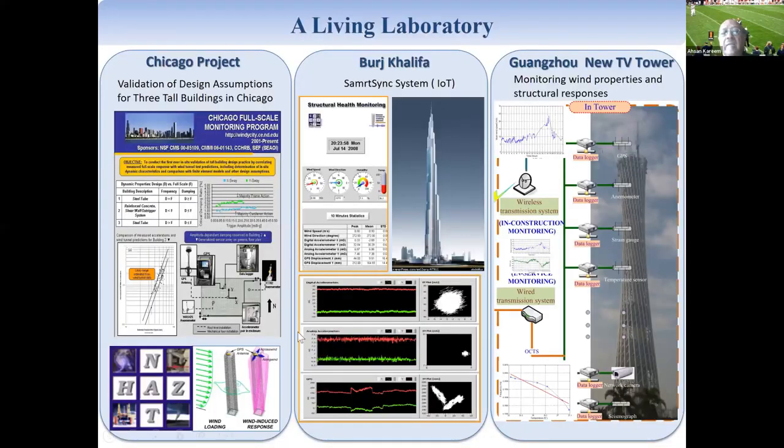Just one slide: there are a lot of buildings monitored. The Chicago project many years ago was Dr. Tracy Kijewski's doctoral dissertation. And then we went to Burj Khalifa, and we had access to the data in one of the world's most instrumented buildings, a tower, which was utilized in analysis of results. In this particular workshop, you won't get much more into this, but this is becoming very critical. And now, especially, monitoring the facade and the cladding is becoming very important. And we have very special types of crawling robots and drones going around trying to find out what really happened in this case.